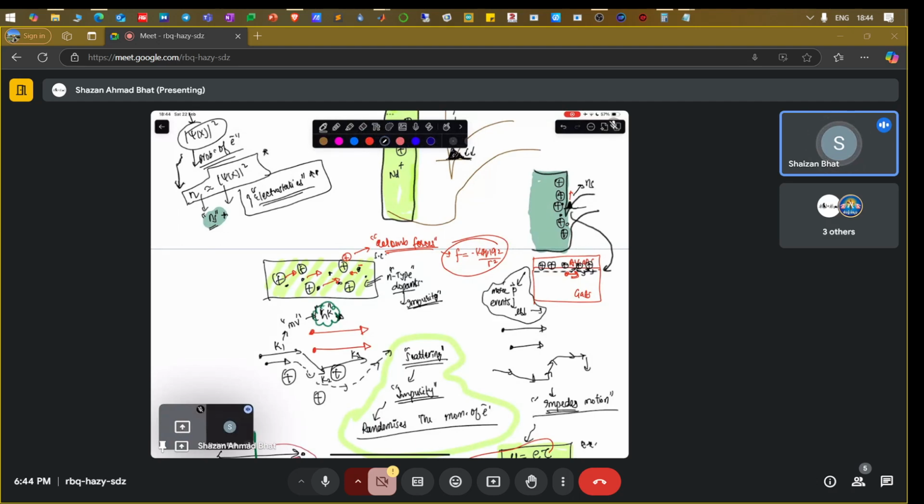Why is the device going to suffer? Because the current is directly proportional to the mobility. So you want the electron to move faster through this channel. But if you have uniformly doped the entire aluminum gallium arsenide layer, then this is going to drastically reduce the mobility.